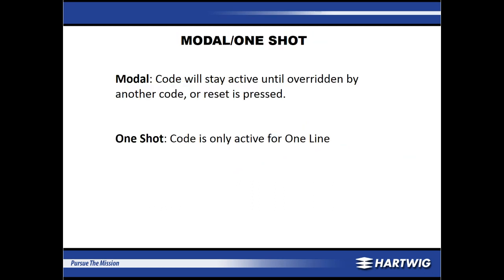Another thing we need to consider about our G-codes whenever we get into them really early is whether our codes are modal or one-shot codes. Modal codes will stay on until they're overwritten by another code, and a one-shot code is valid only for the line that it's on.